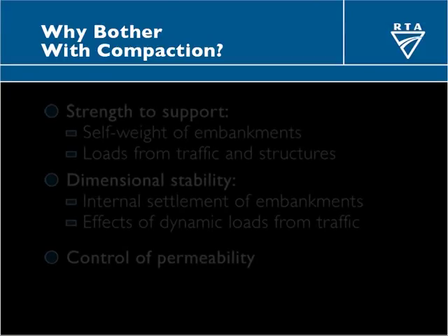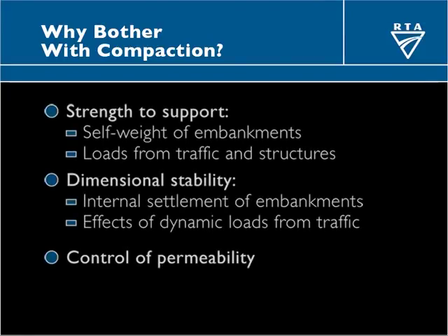Firstly, why do we bother? There are a number of different reasons. Firstly, we're looking at the soil materials having sufficient strength to support, firstly, their own weight, what we call the self-weight, and also live loads or fixed loads from traffic and from structures, which may be supported by it. Obviously, in our case, traffic is always there. Structures may or may not be. That can include things like bridge abutments, it can include noise walls, many other things. Signposting is another.